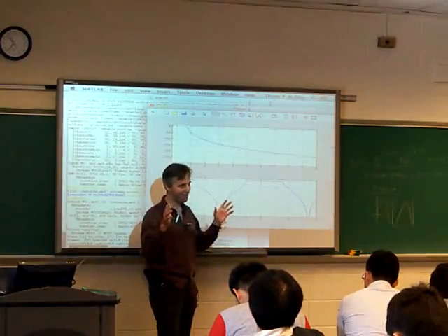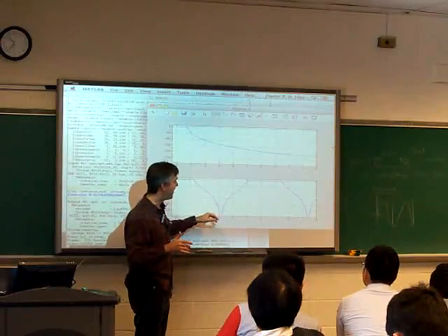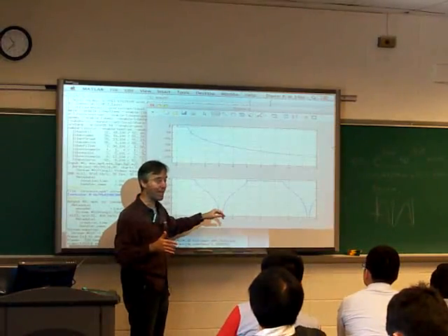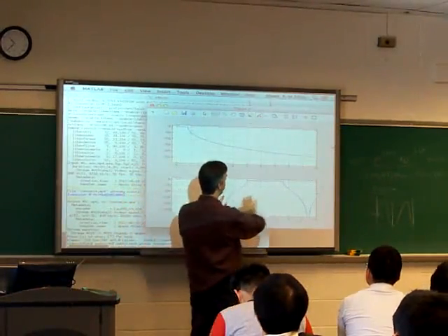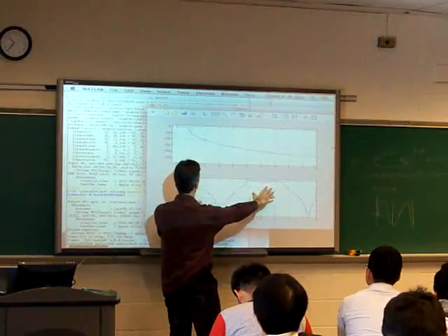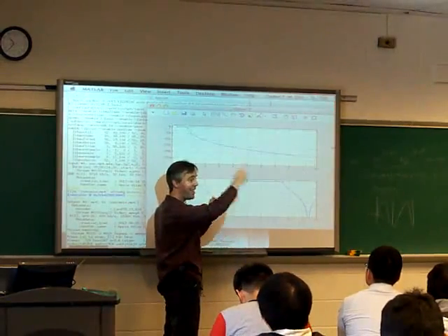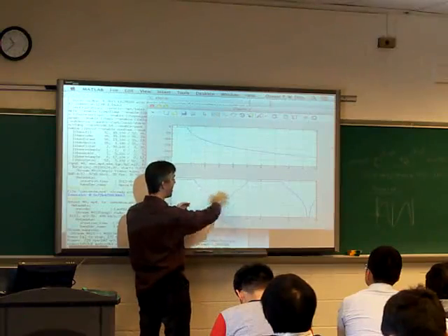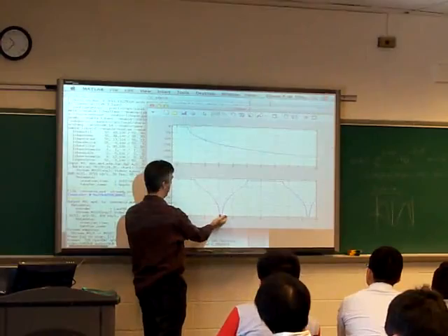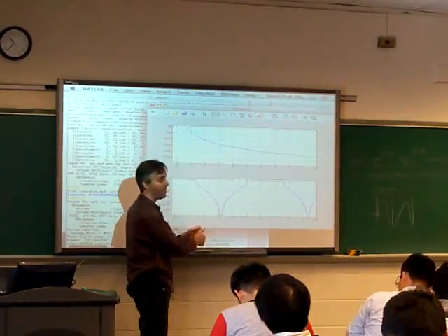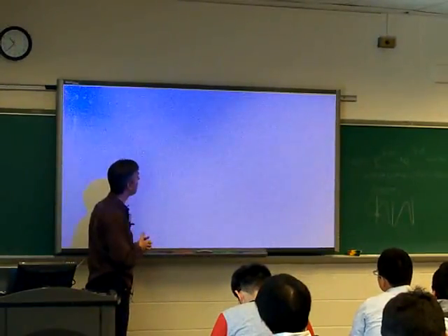So maybe this plot is a little bit confusing, but I guess it's important that we remember that's what it's going to look like when we plot it like that. So basically, we can't control these things independently because they're just taking the values, going round the unit circle on the z-plane again and again and again. So they're going to repeat inevitably. But we can control these range of values. That's the filter design, and that's the game we're in.